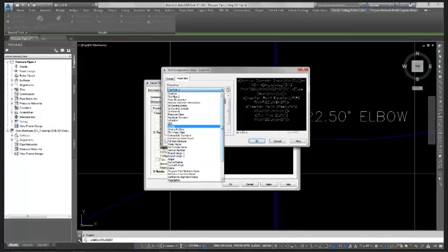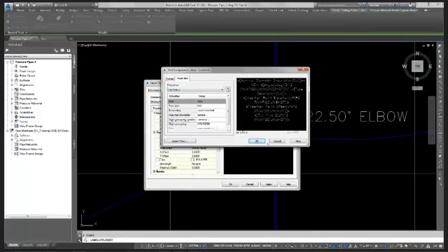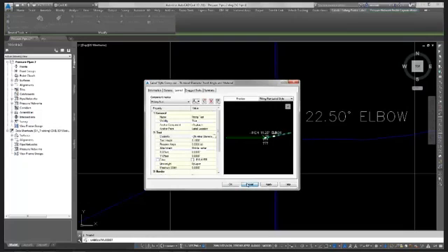The only thing I really have is the insertion point elevation, and that is the center line of your fitting. So if I labeled that in it, it would only give me the center line of that fitting. I don't have the capabilities right now to actually put in the top of fitting as an elevation. That's one of the downfalls. But coming in, okay, cancel out of this.